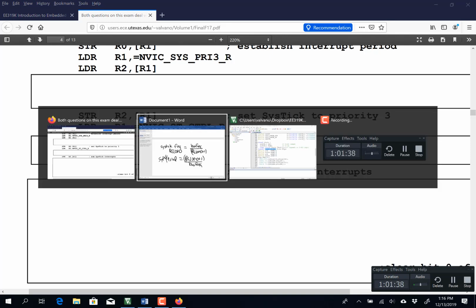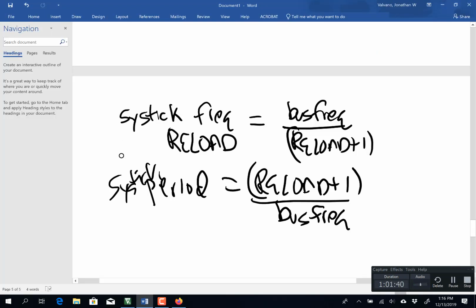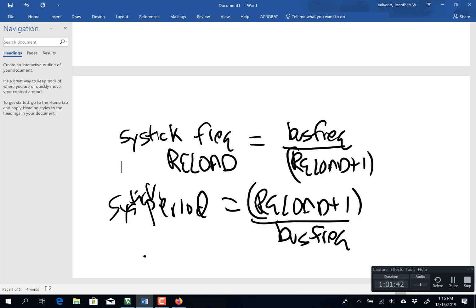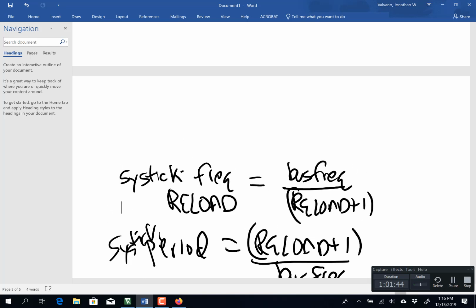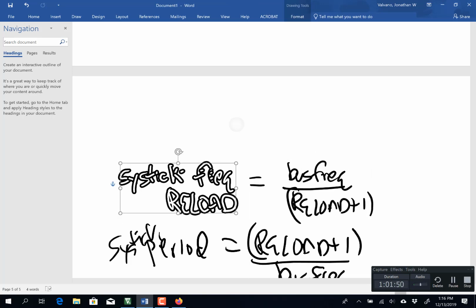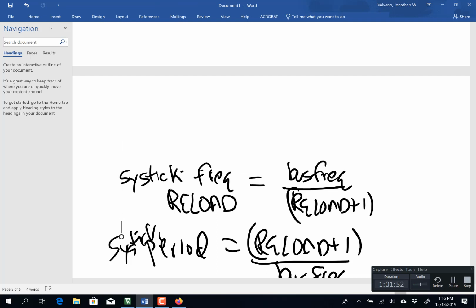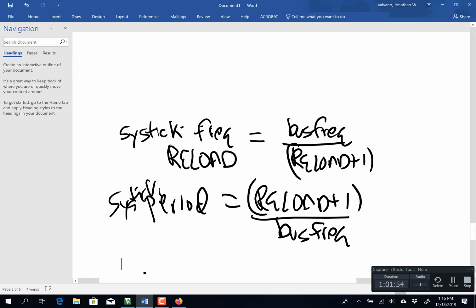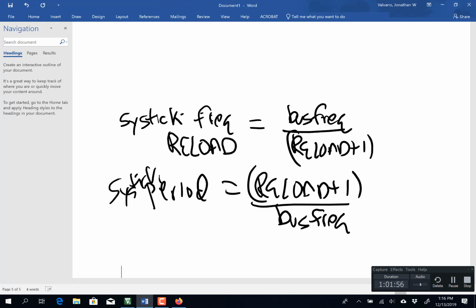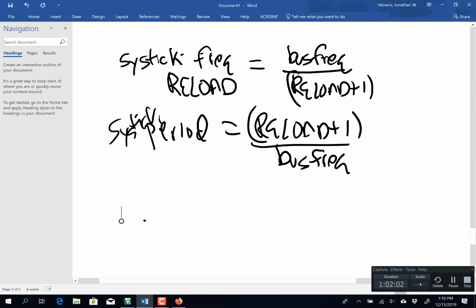So when we first learned about the AAPCS rules, we learned that we should push registers R4 to R11. And then when looking at one of the exams, it said which registers should you not push, and it said those exact registers. Well, then it's a typo. The ARM architecture procedure call standard.